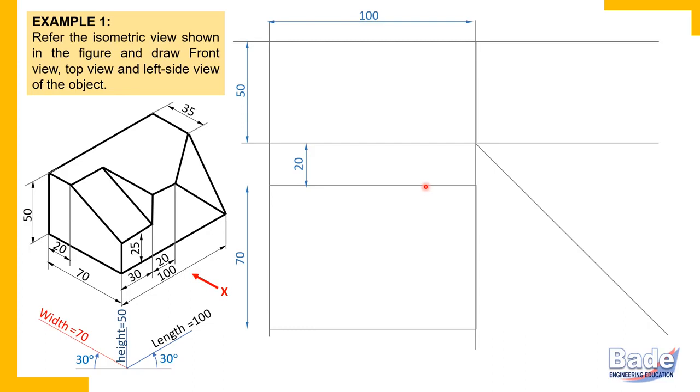In such problems, it is very important to label the XY line. In orthographic projections of machine parts, you need not label the XY line. But still you must know that between the front view and top view there is an XY line. You need not draw that XY line. If your college professors insist on drawing the XY line, you should do that, but it's not necessary.